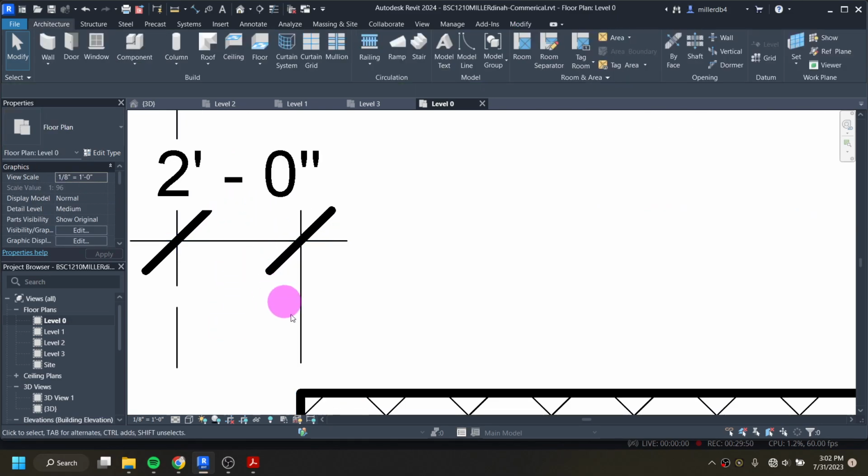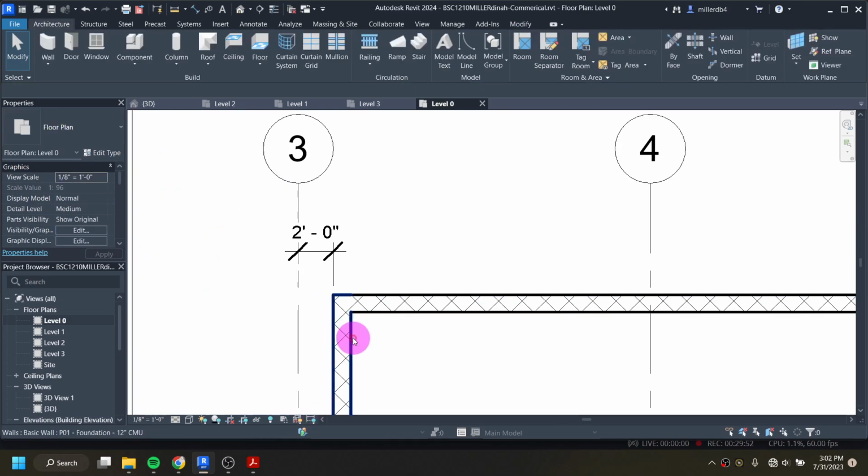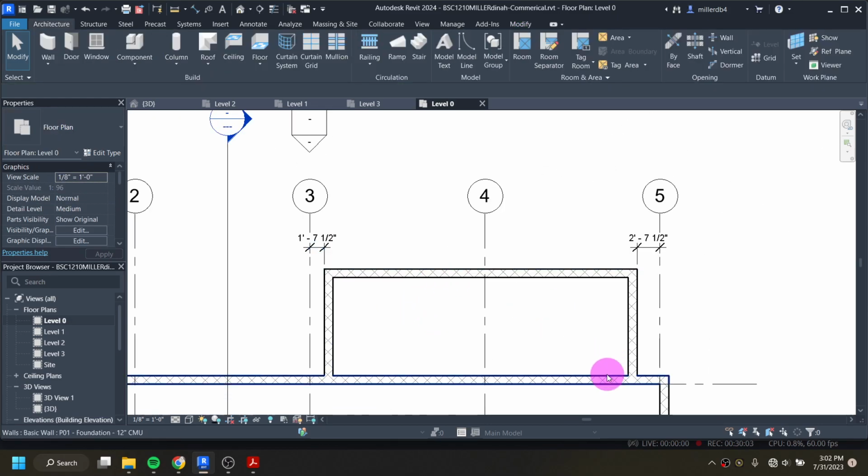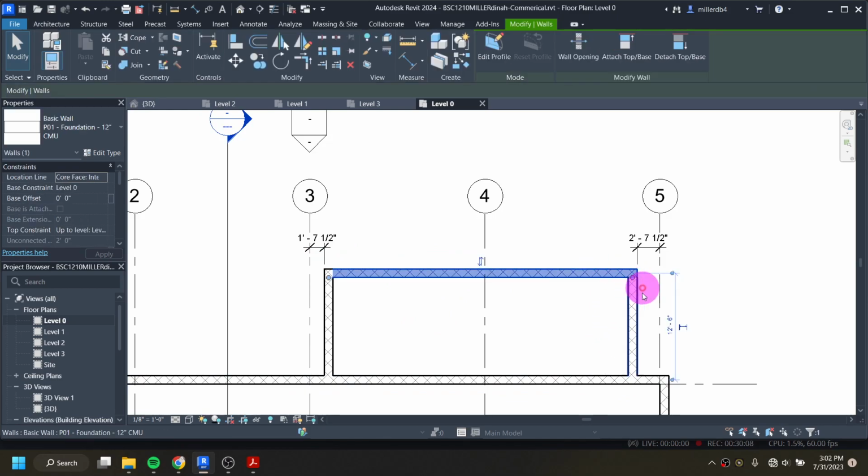This one I'm going to have to zoom in on a little bit in order to differentiate between the witness that's going to the middle or this one. 1 space 7.5, enter. We also need to frame it in this direction, which from center to center here, just because I have another version sitting in front of me. And so it's showing me that the witness lines from the middle to middle is going to be 11 foot 1.25. This is one that I left out of your drawings by accident.